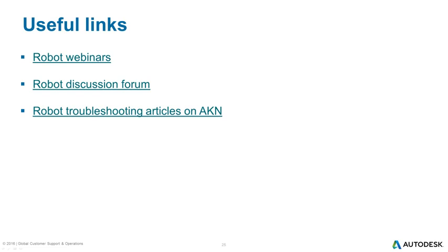Can we do the same analysis for a customized steel plate? The model doesn't really matter. You can create any model and run footfall analysis. This is not linked to a particular type of model, so you can, absolutely. Usually you separate a floor from the building, but how the floor is constructed is how it is constructed, so you should model it exactly as it is.